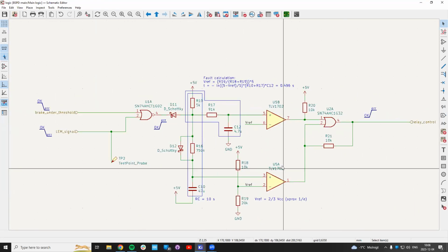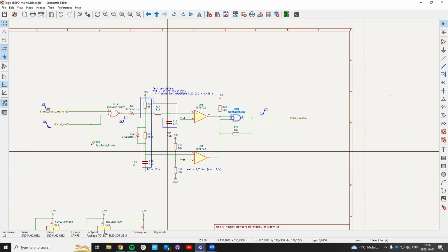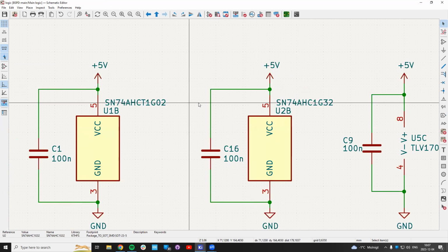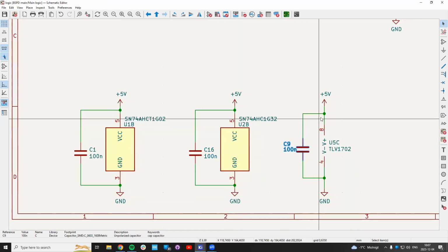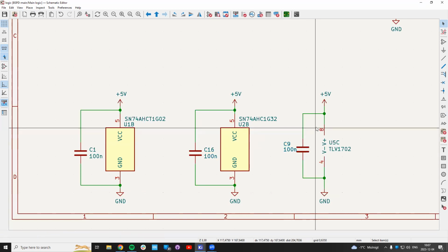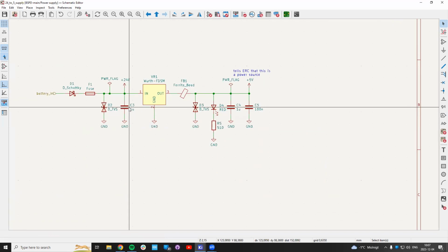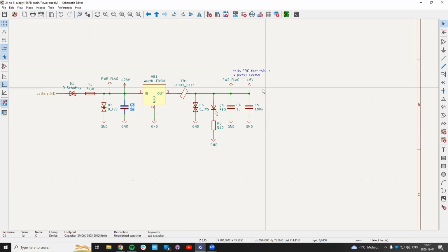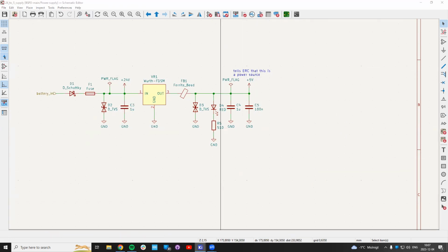And yeah, if you have things like an OR gate here, U2, it's powered by this block, so these are the pins. You want to make sure that this capacitor is actually close to the pin. That is a very important thing to remember. As soon as you have capacitors, you want to keep them close. So that also goes for the power supply. These capacitors should be close to this because it's filtering. We're removing noise, and you want to remove it at the source and supply it as close to the components as possible.